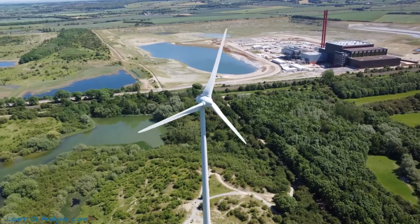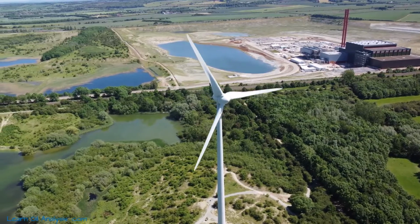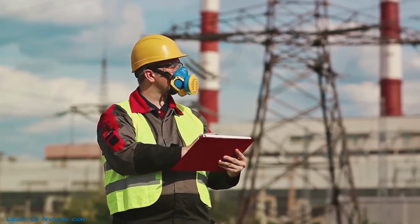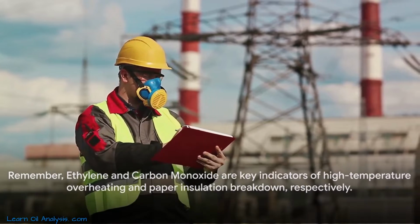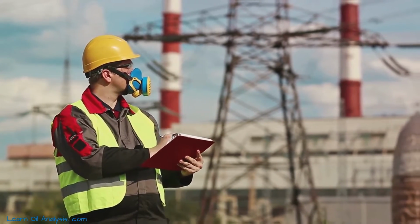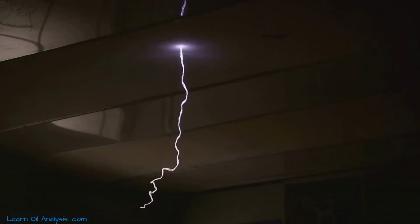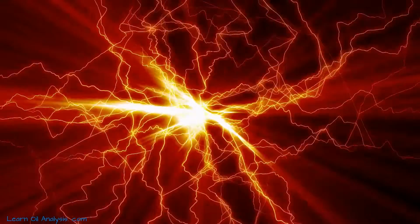Ethylene signals high temperature overheating, while carbon monoxide points towards paper insulation breakdown. By keeping an eye on these gases, we can ensure our transformers continue to operate efficiently and safely. Remember, ethylene and carbon monoxide are key indicators of high temperature overheating and paper insulation breakdown, respectively. The presence of methane and ethane in the oil sample can suggest that a low temperature less than 300 Celsius or mid-range, 300 to 700 fault is in progress.